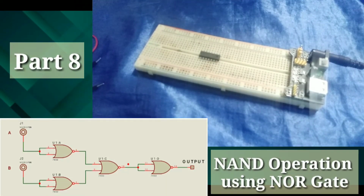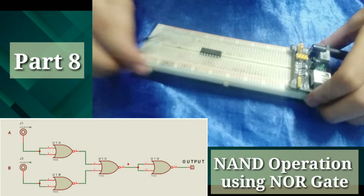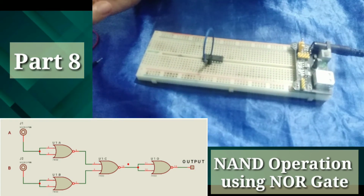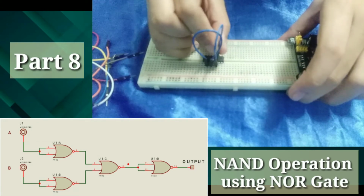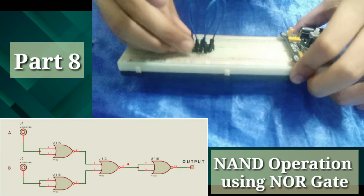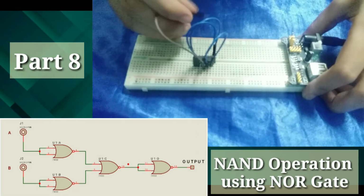Now, for part 8, NAND operation using NOR gate, we will be needing a 7402 integrated circuit. As you can see, pin number 2 of the IC is connected to pin number 3. Pin number 5 is connected to pin number 6, just like this one. Then, pin number 1 is connected to pin number 8 of our IC. So, dito yun. Then, pin number 4 is connected to pin number 9.